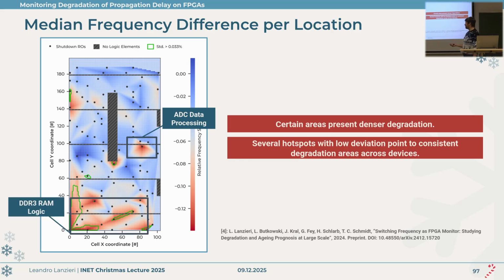And another interesting part, what's going on here, is the DDR3 RAM logic. Because the RAM is connected in pins in this area, we want all the IP cores that use it to be in this part. Again, there is a lot of switching activity and a lot of usage constantly going on in this area, which seems to have aged this area much more than the rest.